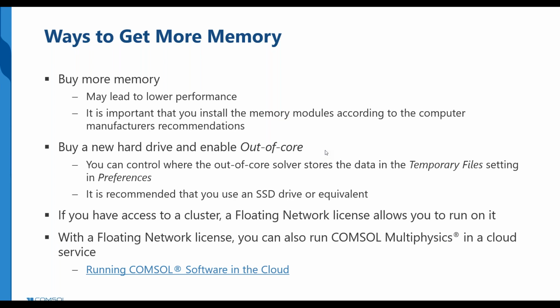You can expect a better memory bus, but if you really want to see, it is the access time of memory that is important. So how long does it take to fill my cores with new data from my memory? And that you can see in data sheets if you really want to compare. But it's a good question, because looking at memory buses and their characteristics is more important than looking at the clock frequency and the number of cores of your processor. So that's a good question. I will take more questions later.